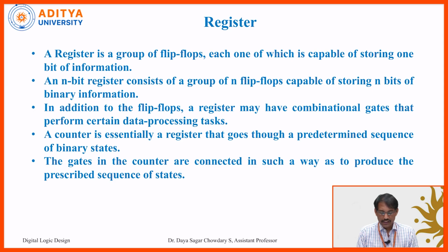A counter is essentially a register that goes through a predetermined sequence of binary states. The construction of registers and counters is almost the same. Depending on the flip-flop construction only, these two, registers or counters, may differ. There is a little difference between the two. The gates in the counter are connected in such a way as to produce the prescribed sequence of states. We will discuss all these things in the next slides.